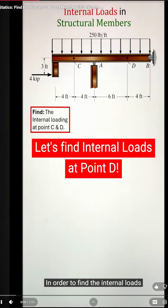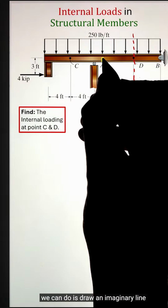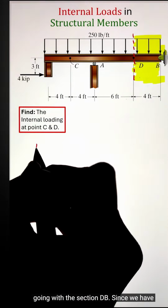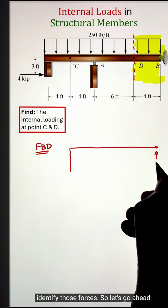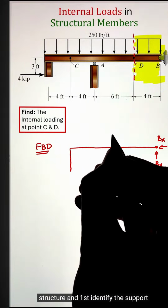In order to find the internal loads at point D on the structural member, what we can do is draw an imaginary line and divide the beam into two halves. Next, we can select any one of the halves to solve for the internal loads. Here we are going with the section DB. Since we have a support reaction at point D, we need to identify those forces. So let's go ahead and draw the free body diagram of the whole structure and first identify the support reactions